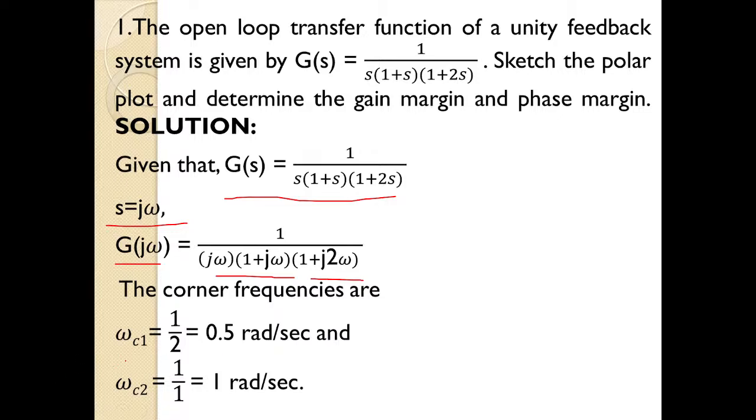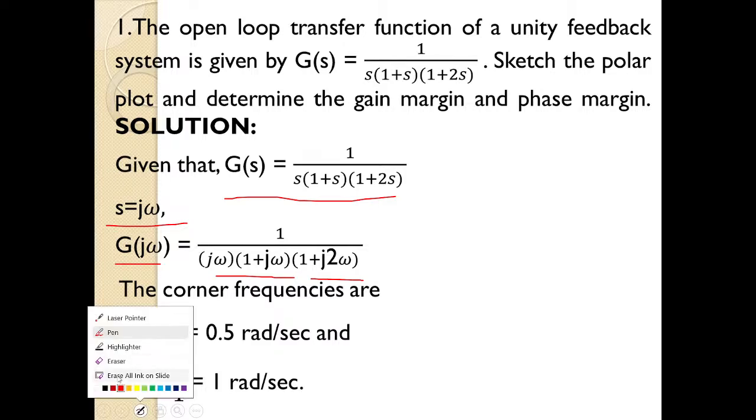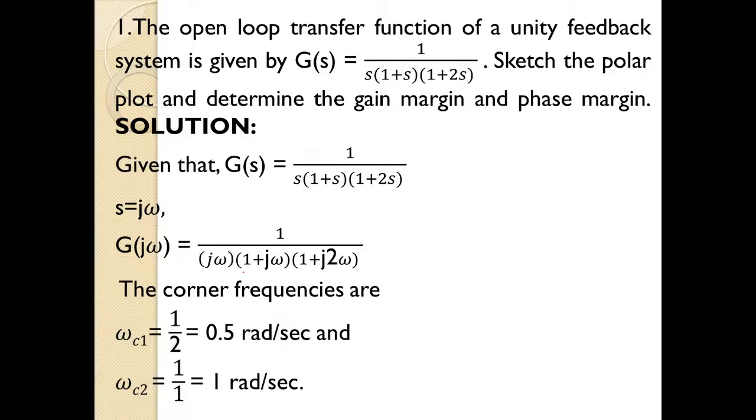Now we have two factors here, isn't it? Two first order denominator factors are there. For these two first order denominator factors, we can determine the corner frequencies.